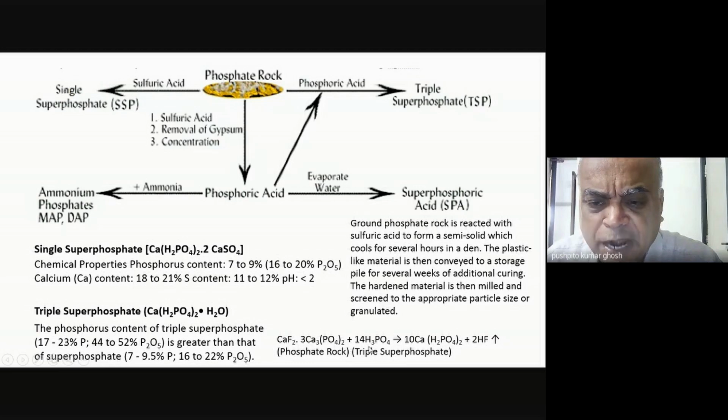But if you were to write down the equation, you can write down this. Okay, and this is effectively this molecule. Okay? This is what you're forming. Okay? Since we found that these rock phosphates have 3 to 4% of fluoride, obviously the fluoride will get also protonated, and the first molecule that you'll form is HF. Okay? But the HF, actually all of it does not get released during the manufacture of phosphor-based fertilizers. Some of it remains.